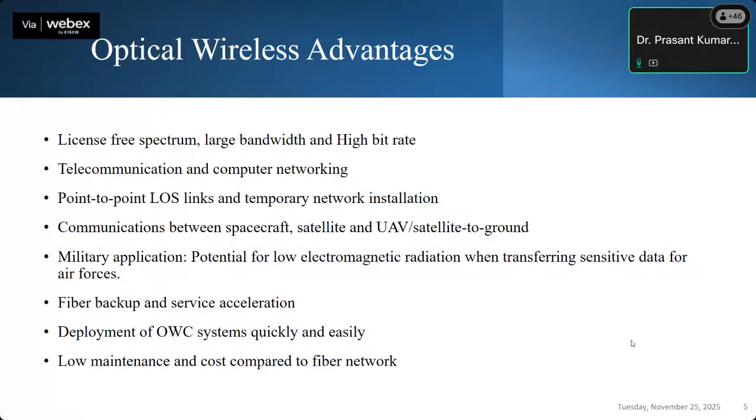And this optical wireless can be used as a backup to fiber-based networks for service acceleration. It can be deployed very fast. The deployment of an OWC system requires hardly a few hours, maybe 4 to 5 hours. So it can be used as a communication link for disaster recovery scenarios where all your networks are down. At that point, one can deploy an OWC system, and you can attain all the features like ultra low latency, very high data rates, high bandwidth, low bit error rates.